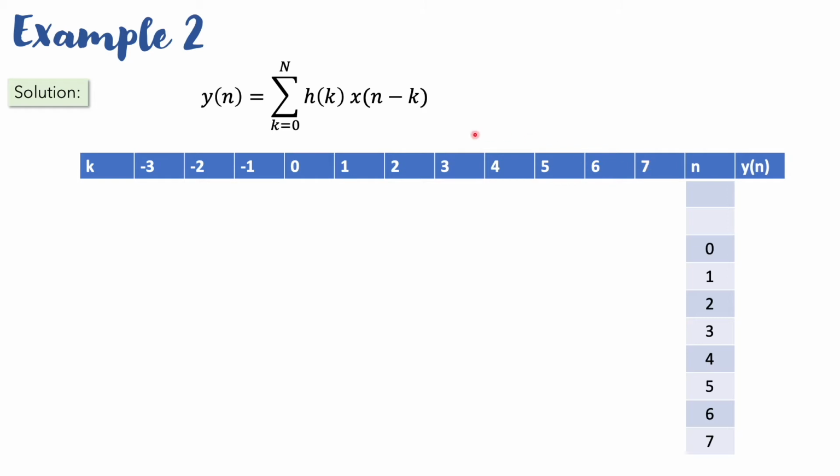Here is the one that we want to shift, the shifted input sequence. Since x had 4 samples, we need to flip it in order to obtain this one, n minus k. You remember in the first or second lecture we shifted a signal like this. At first we need to flip it, meaning x[k] will be flipped to get x[minus k], and then we keep on adding the value of n, meaning 1, 2, 3, as we shift it towards the right.